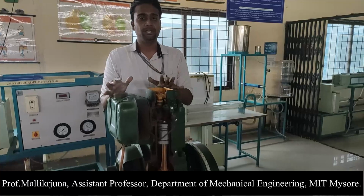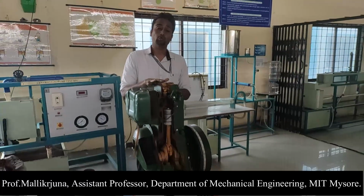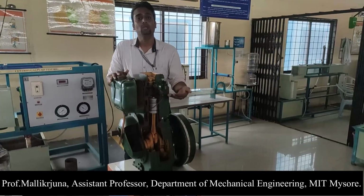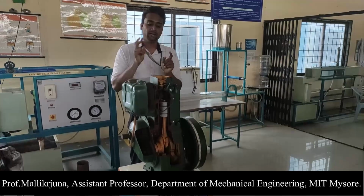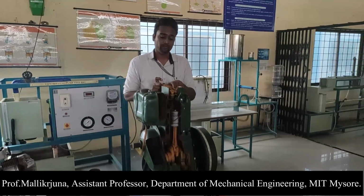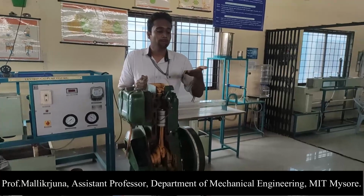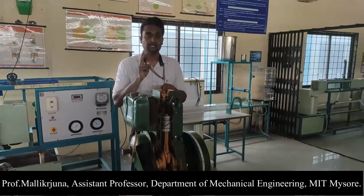Let me clear the readings now. Very first thing I have seen is inlet valve closing. Inlet valve closing happens after the piston reaches the BDC. I mean, during the starting of the compression stroke, the inlet valve closes. Second reading is opening of the exhaust valve. Opening of the exhaust valve happens before the piston performs the complete power stroke. That means before the piston reaches the BDC, the exhaust valve opens. That is the second reading.